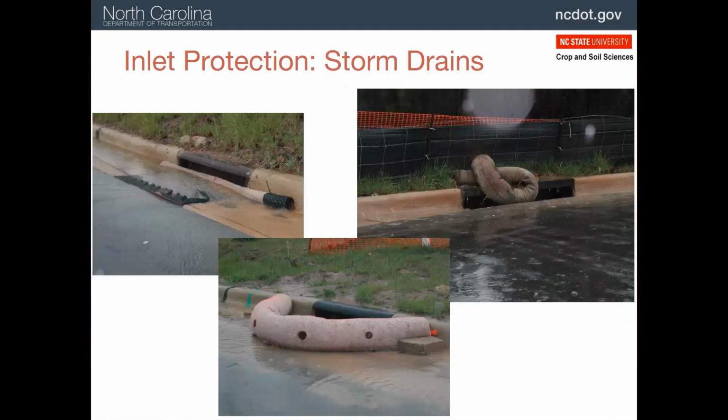So especially the ones that go inside the drain are prone to fill up with sediment. So you need to keep track of those before they actually will burst and release all that sediment into the pipes. You also have to make sure everything's still installed as well.